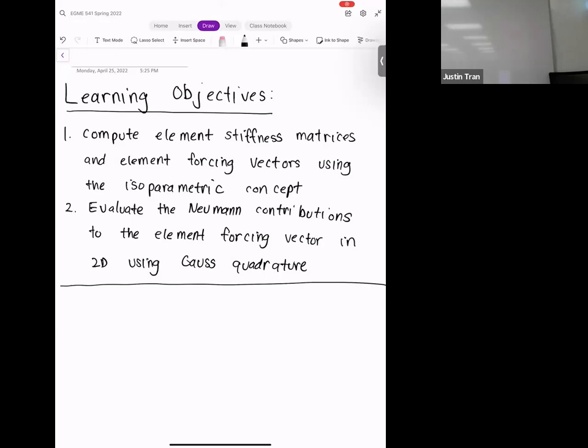But then they want the weak form, right? And assuming a linear weighting function. So we have our fixed condition, and that's at 0, so they're both equal to 0. On the other end, this is both equal to 0. So then we end up in this situation, and then we have this. And we do have the Neumann condition at the end, 10 kips.